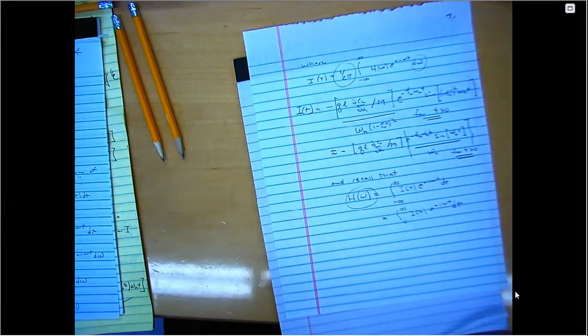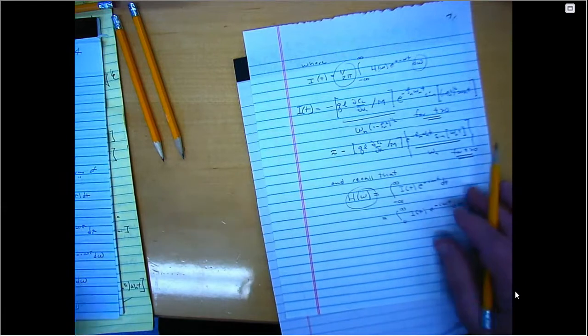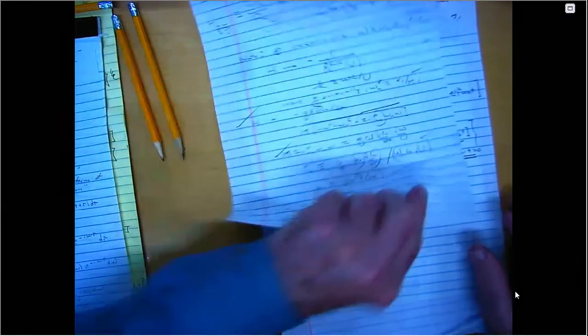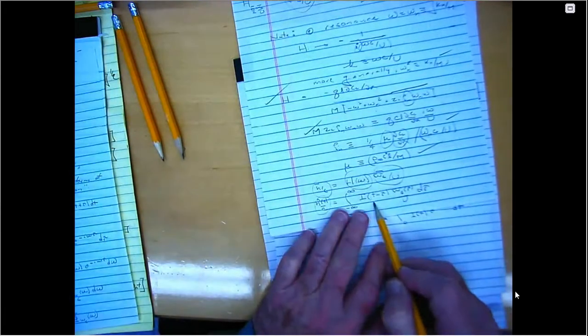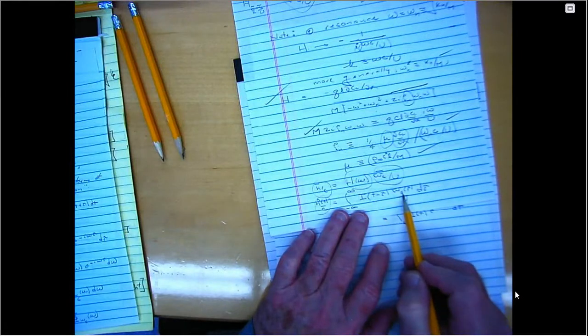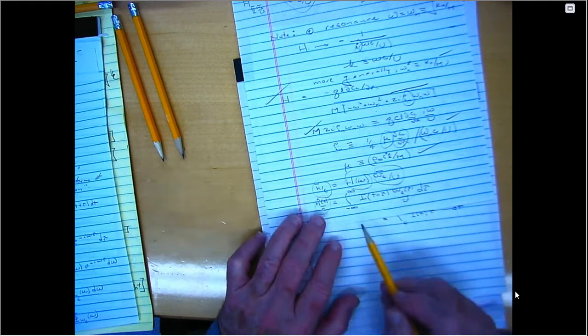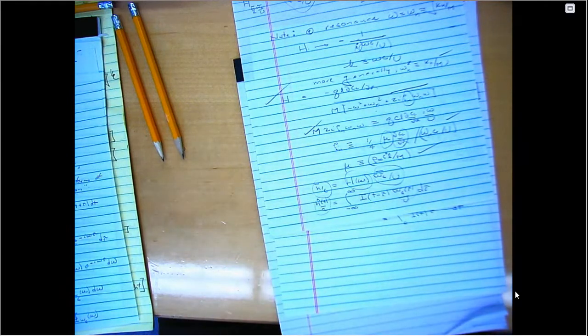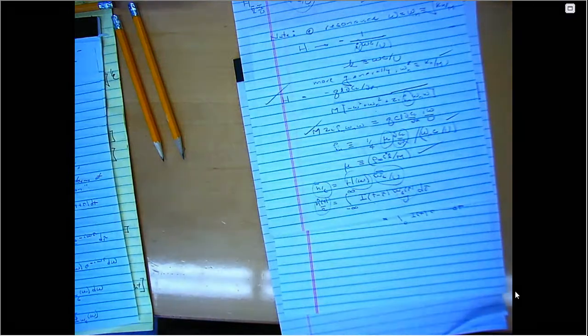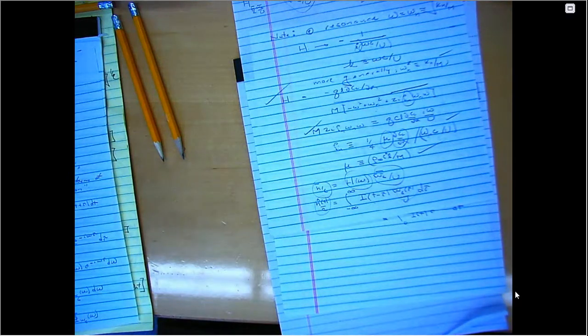So we're done, right? Why? Because from this expression, I now know the response to any gust. If I can perform this integral, I can determine the response. And I don't care what the gust time history is. It could be a random function of time, right? It could be any other function of time. This is it. This is the whole story. I start out with simple sinusoidal motion of the gust and of the response, and then I go Fourier transform. That's all.